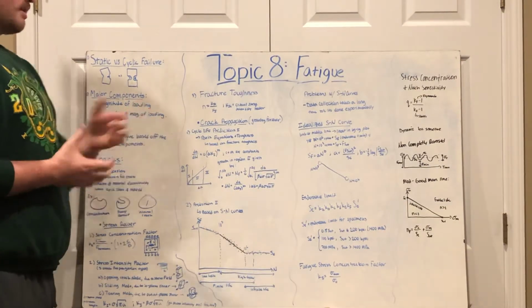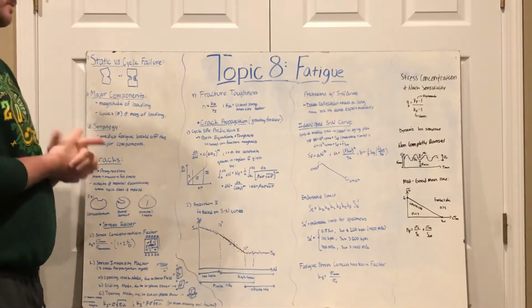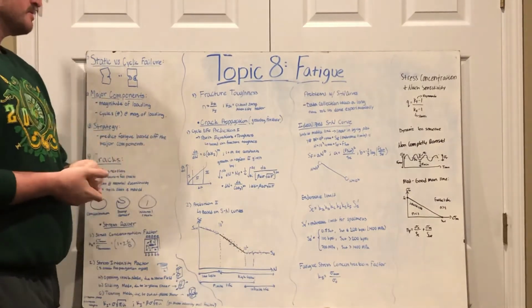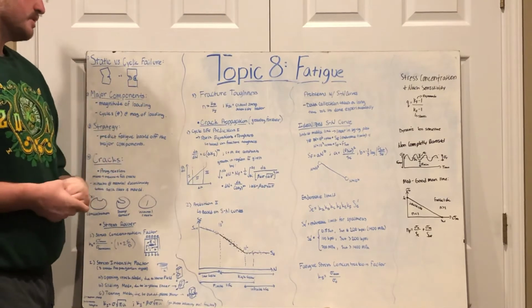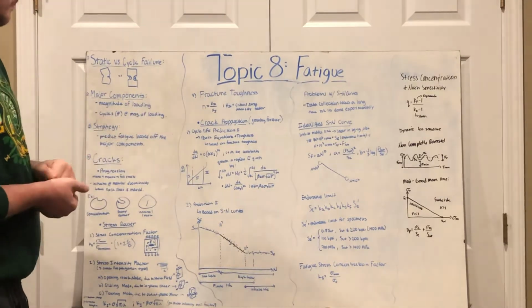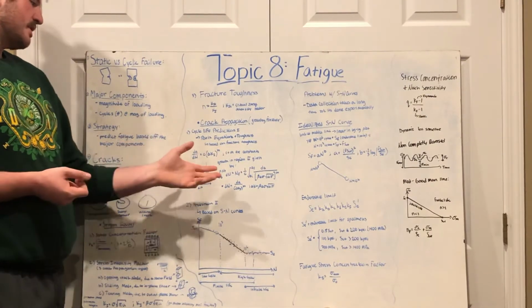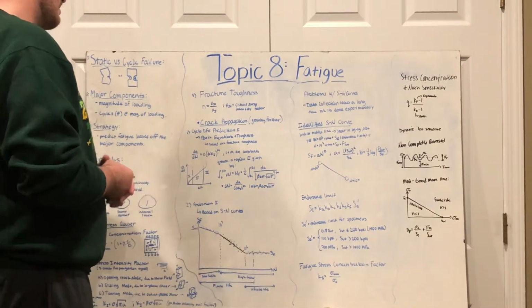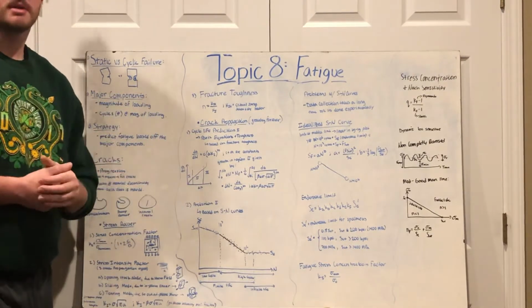We can look at it in two ways. The first is the cycle life prediction, given by the Paris equation and toughness, which is based on fracture toughness, as given here. The Paris equation given here is da/dN equals C times delta K_I to the m, where C and m are both constants given by tables in the book.